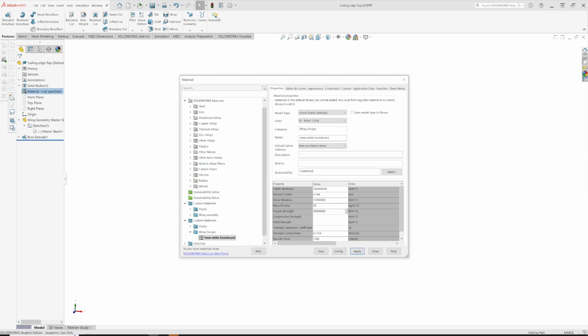Tensile strength, actually we don't need this because you only use it in automated calculations. I can put it in just because we've got it. So the ultimate tensile strength is 1.3 times 10 to the 6. And our compressive strength is 1E6. When you do some modelling, you can sometimes use these and it'll tell you you've exceeded your stress value, but we'll put those in just because you might use them.